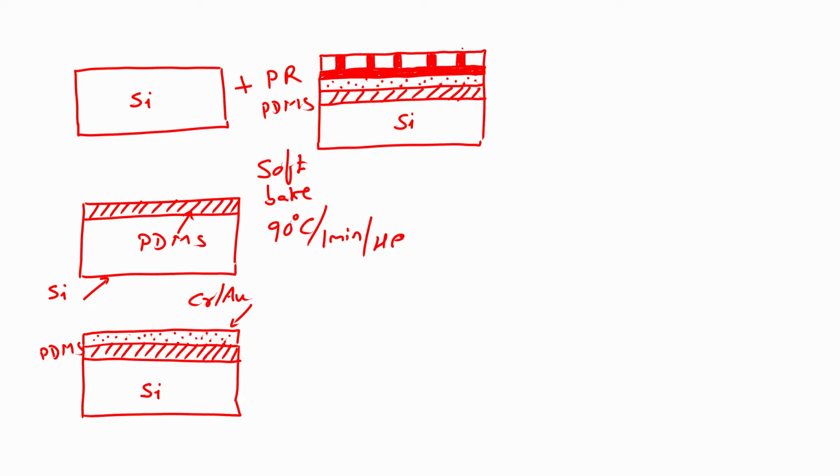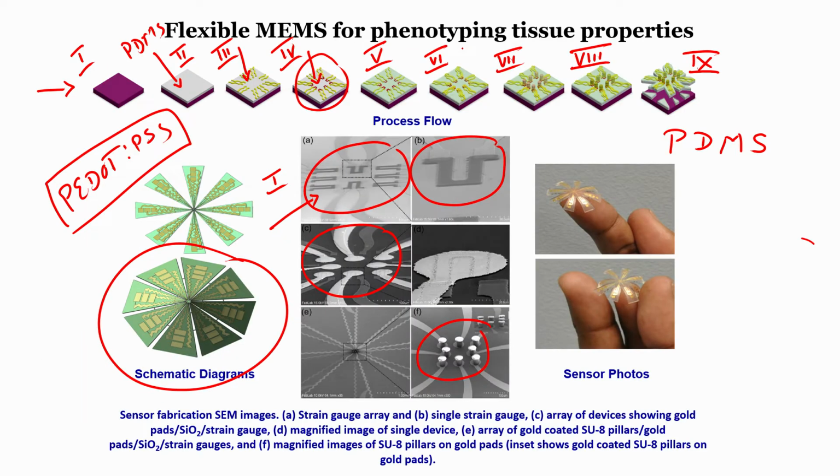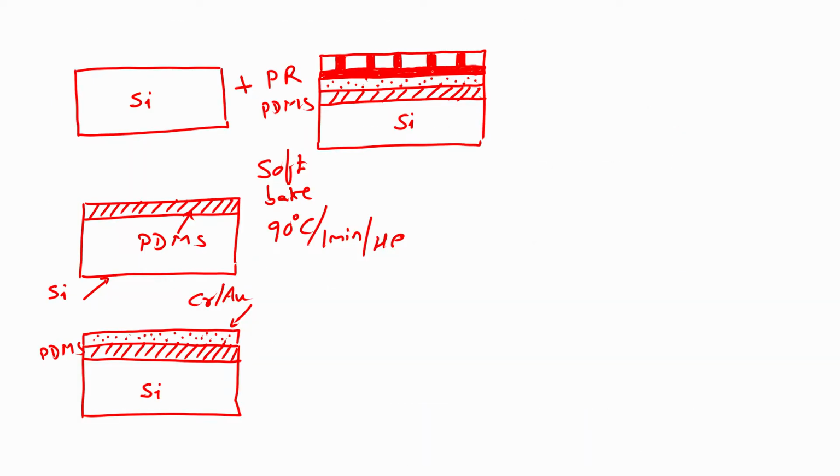So, if I take a cross section, you see this particular first step, silicon substrate, we can also have oxide, and then we have PDMS, then we have to pattern this. So, if I take a cross section, I will be able to only see this kind of layers, and that is why we have been representing the bright field mask in this particular format.